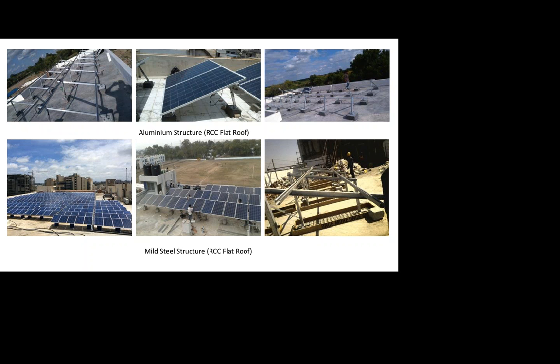In this case, if your table size is going more than 4 meter in height, we recommend going with a double post design, a front and a back. That would help you optimize on steel because moments due to wind force will be reduced. The turning thing, right? If we support it on the front and back, it is difficult for wind to turn it around. So that is how we are doing it.